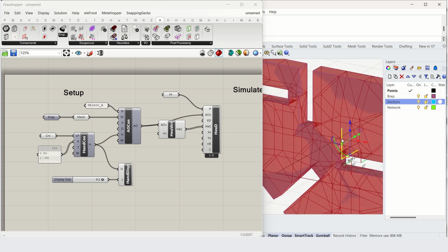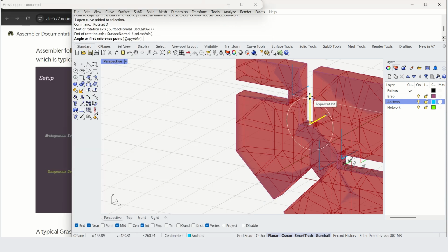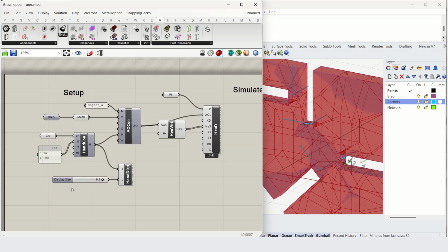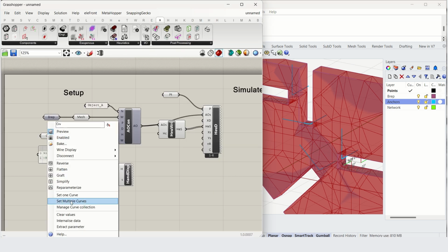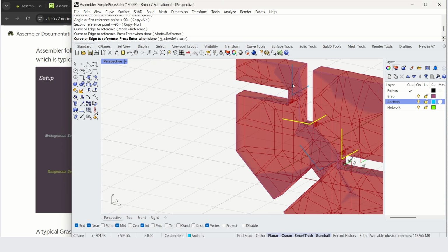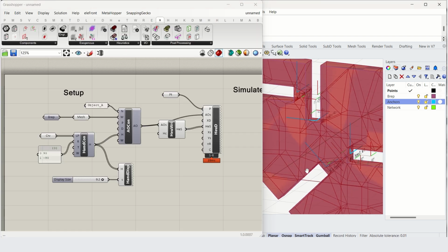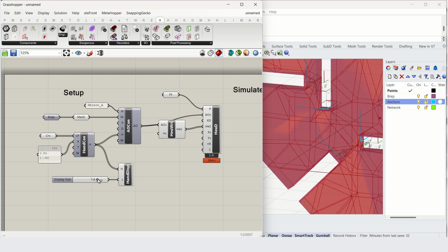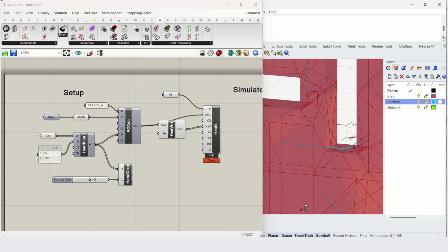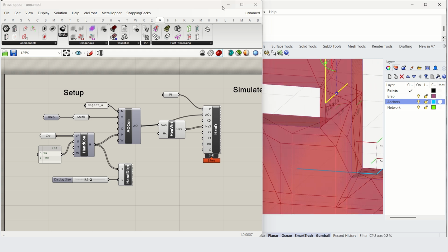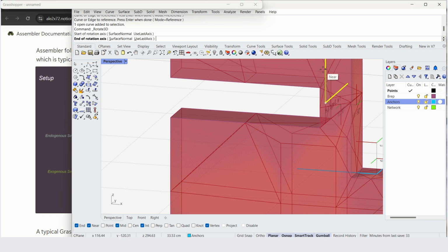Before continuing, add any other notches as handles by copying and aligning the L polyline and then adding to the curve param. Use the handle display to check that none are projecting into the volume of the piece. If they are, rotate them 180 degrees so that the display is projecting back outward.